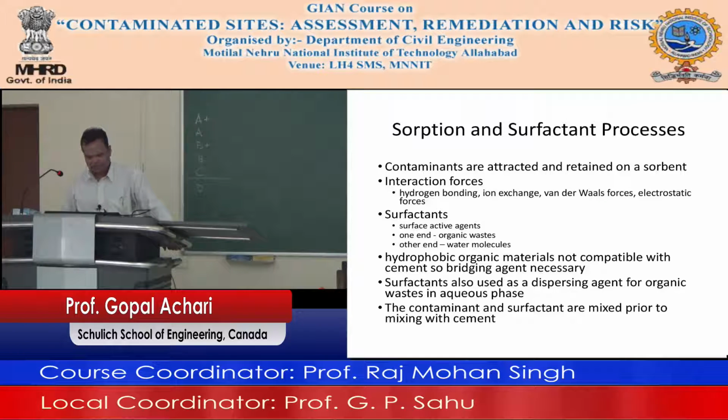The contaminants and surfactants are mixed prior to mixing with the cement. So you mix the contaminant with some surfactant, and then you mix the cement, because the contaminant and the hydrophobic end of the surfactant will bind together, and the hydrophilic end will be available for the cement to attach. We'll come back to that in a bit.